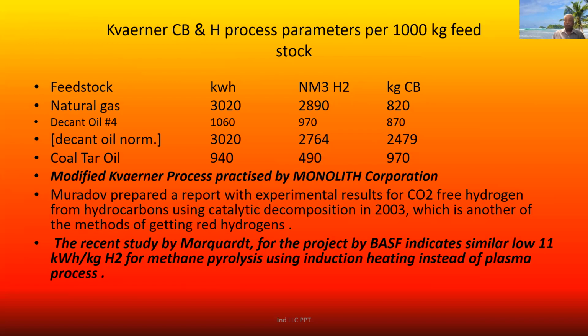The recent study by Marquardt indicates the BASF process being developed in Germany by Andreas Bode's group, and in some of the labs in the US, requires 11 kilowatt hours per kg for methane pyrolysis using induction heating instead of a plasma process.